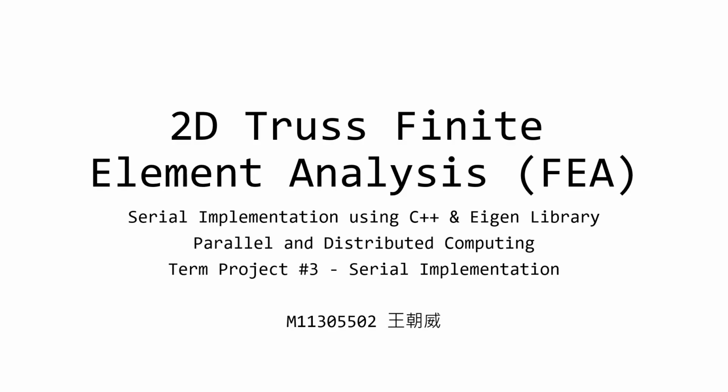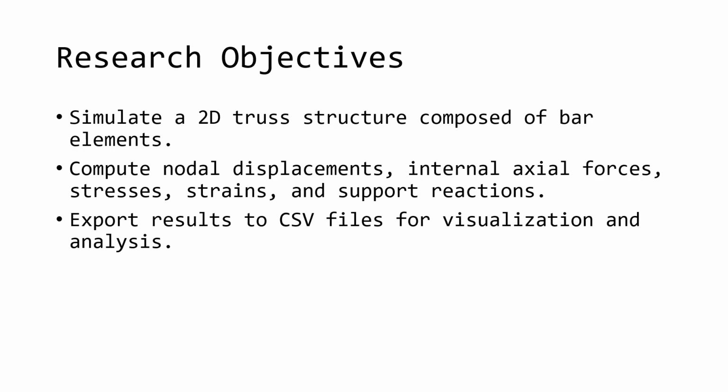Hello everyone. Today I will be introducing my term project, the 2D Truss finite element analysis, using a serial implementation in C++. The main goals of this project are to simulate a 2D truss structure made up of bar elements, to calculate nodal displacements, internal axial forces, stresses, strengths, and support reactions, and to export the results into CSV files for easier visualization and further analysis.